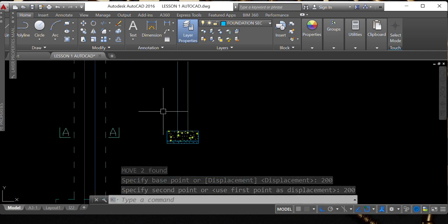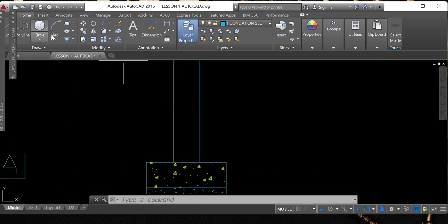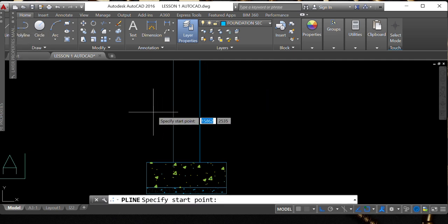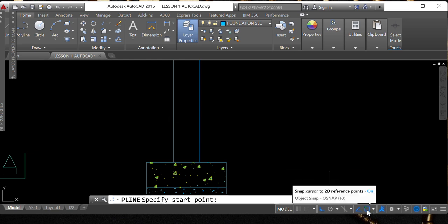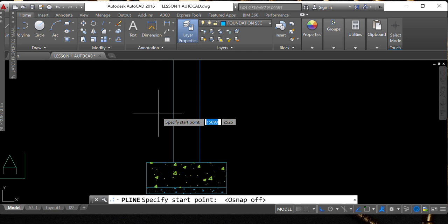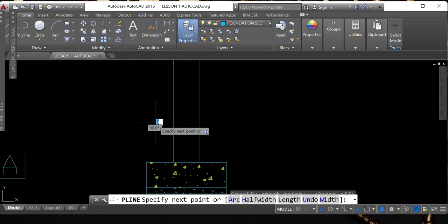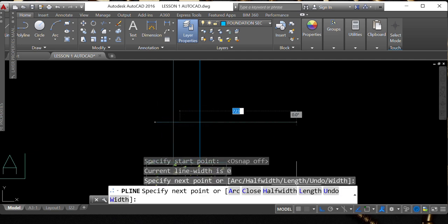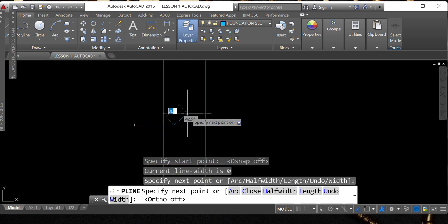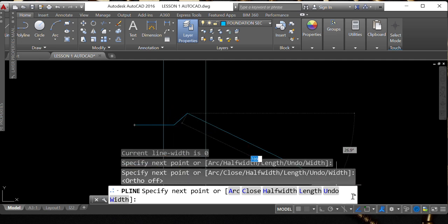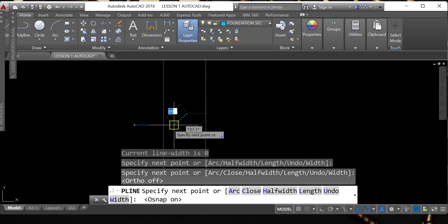And then I want to introduce the break lines here. I use a polyline, and then I'll put the snap off. Here, put the auto mode off, so that you can do an inclined line. Put back the snap on. I want to snap this horizontal.